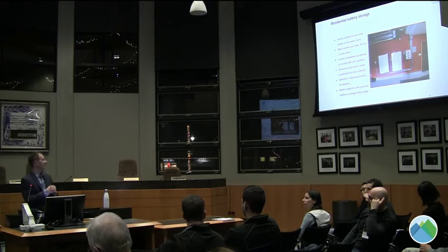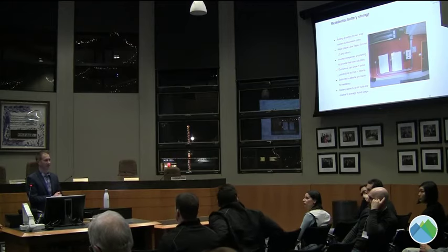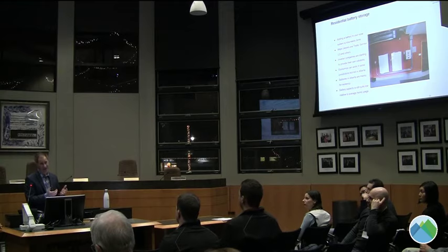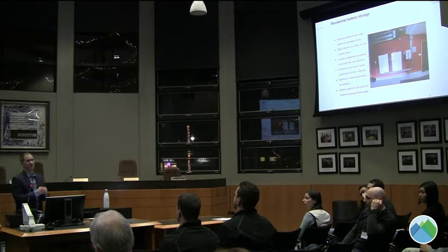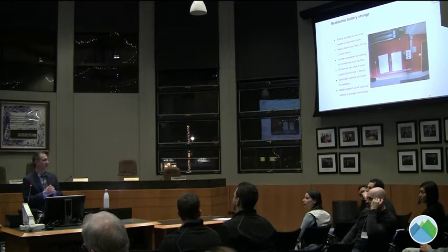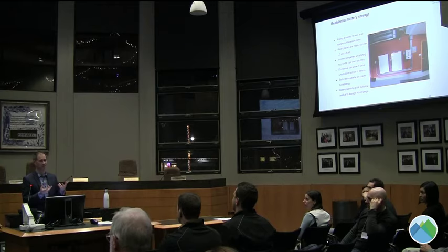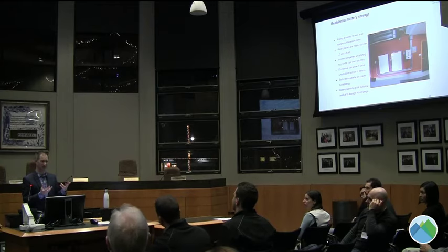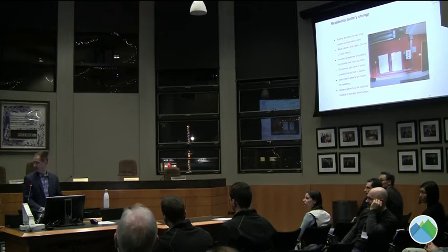I mentioned already, economics can work, but not in Alberta. And right now, if you're buying a battery in Alberta, you're buying it for resiliency. You're buying it for power outages, or maybe off-grid, but not if you have access to the grid. You're probably not going to do that. The other thing I would talk about is battery capacity. So a Tesla Powerwall, there are two Powerwalls on that wall. They do about 13.5 kilowatt hours each for storage. An average home uses about 27. So you really would need at least two of them to be able to get storage for the course of the day, which can come up in price, to back up your home. To be able to cover and run a whole day on a battery.